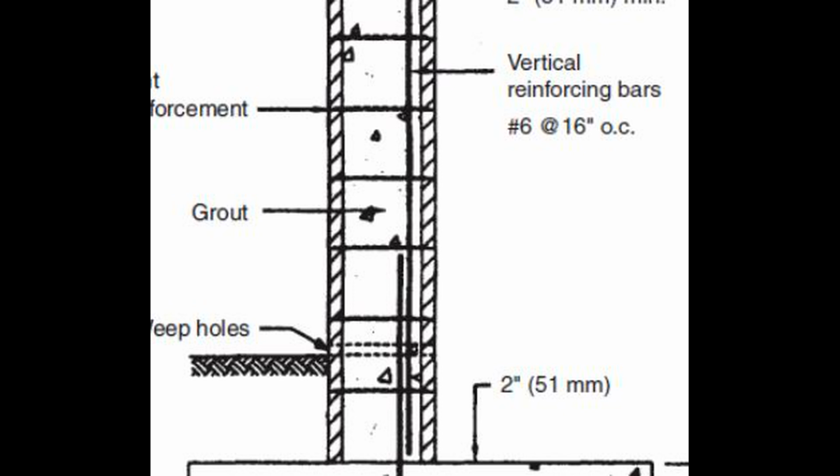And for accurate information, the country standards are required to be referred to. The minimum grade for structural steel reinforcement is required to be grade 500. And again here as well, country standards and codes are required to be referred to based on an engineering design.